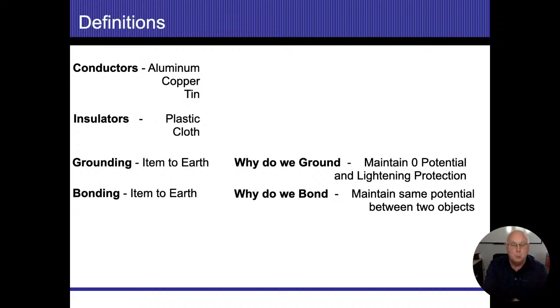All right. The difference between a feeder wire and a branch circuit: feeder wires are going to be coming from either the pole to the panel. They'll go from a panel to another panel. Those are feeder wires. Those, by definition, can actually be solid aluminum, but because of the flow of electricity, I don't think I've ever seen that much. We just can't get that much electrical flow that we're going to need in a house for those connections in a single strand. So solid aluminum, we talked about if it has the plastic insulation. Solid as opposed to stranded, and branch as opposed to feeder. You should be able to identify those.